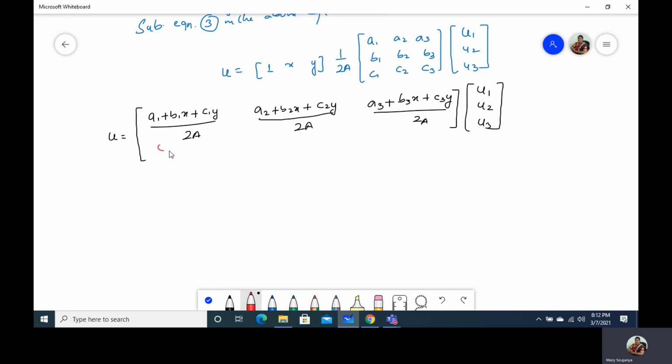If we clearly see these terms, I'm naming them N1, N2, N3 because they are the shape functions. Shape functions are denoted by N, we have already seen that. I'm calling these shape functions because the displacement in the element is related to the elemental displacement at the nodes.